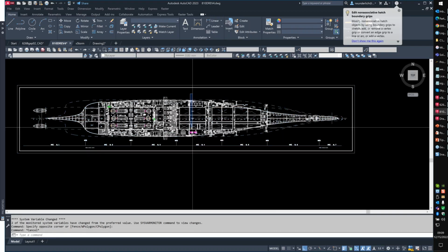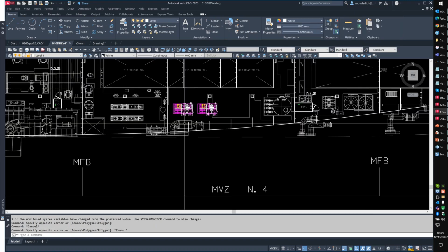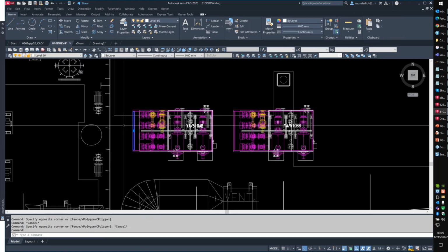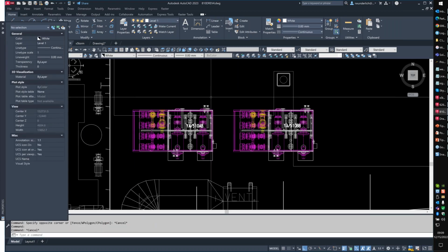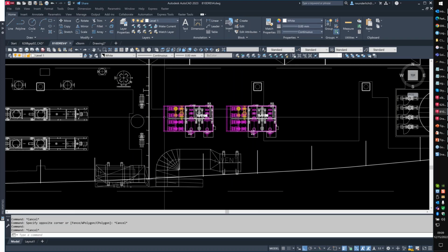Once this is done, these are block definitions, and these did not get updated, and you'll see that it's a block reference, and it's an unnamed block. So what you'd normally have to do without using this command is, if it's a named block, you'd have to go in and change the block definition. If you've got a LISP routine, like I have a couple of LISP routines, I can go through and force everything to color by layer, or the set by layer here is what works out really well.